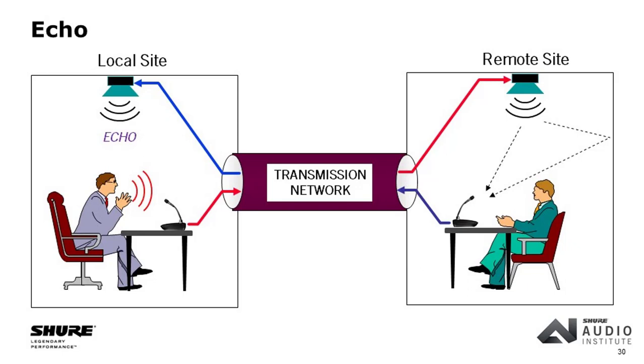Right. And in fact, as you get into more complex systems in larger rooms, you often find that when you have multiple microphones and multiple loudspeakers, the echo relationship between them is all slightly different, which means that you might not be able to expect a single echo canceller to handle all the different acoustic situations there and keep up with it. So it generally is better when you have more microphones to have individual echo canceller paths or channels for each microphone, or at least each section of microphones perhaps.